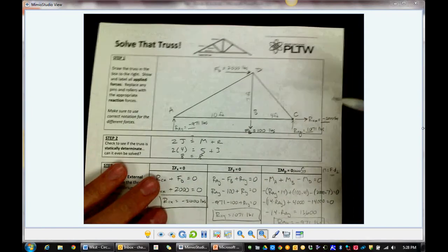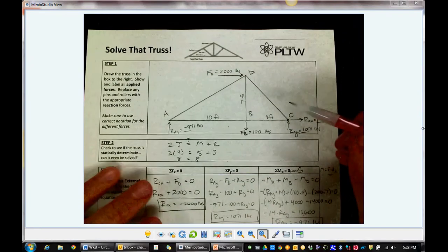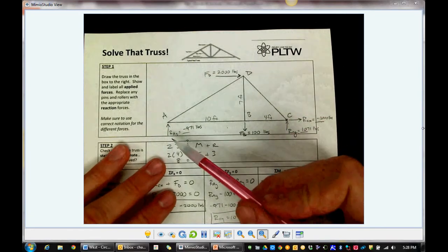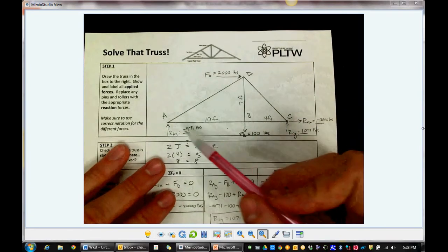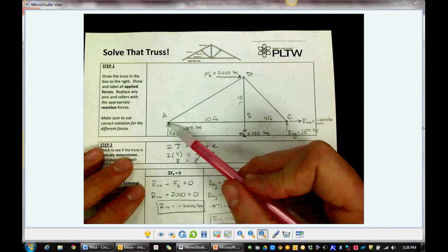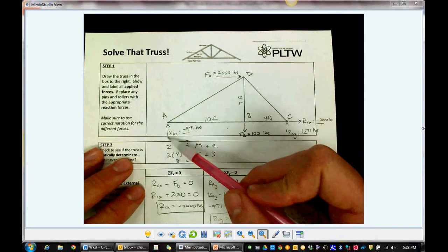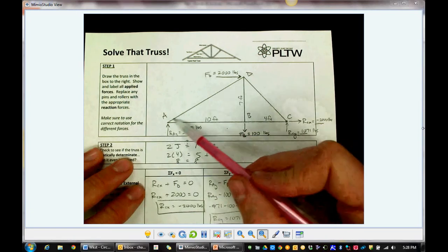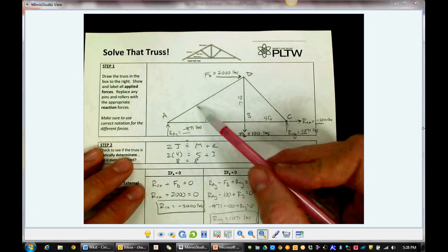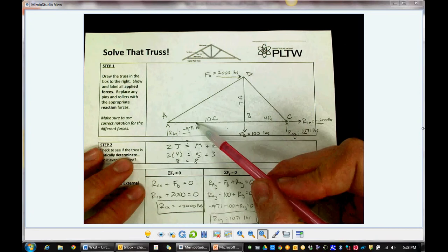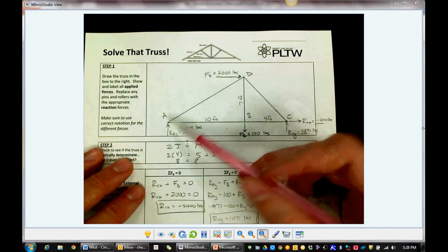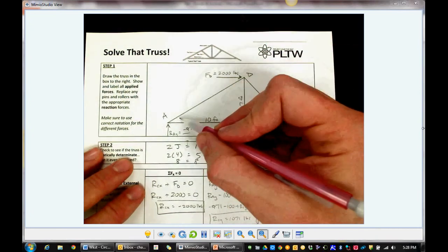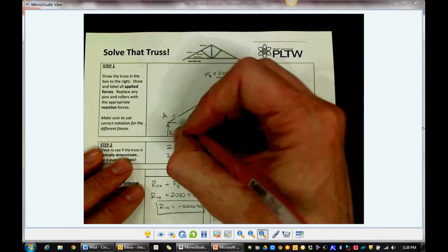So this might not make sense until you see one, but I'm going to go through point by point and just tell you what my thought process is here. If I'm going to draw the free body diagram for joint A, I know this force, but I'm not going to know the force provided by member AB or the force provided by member AD. Two unknowns, we'll have two equations, so I could go ahead and start at joint A. So finding this angle, angle A, might make some sense. Let's call that theta A.